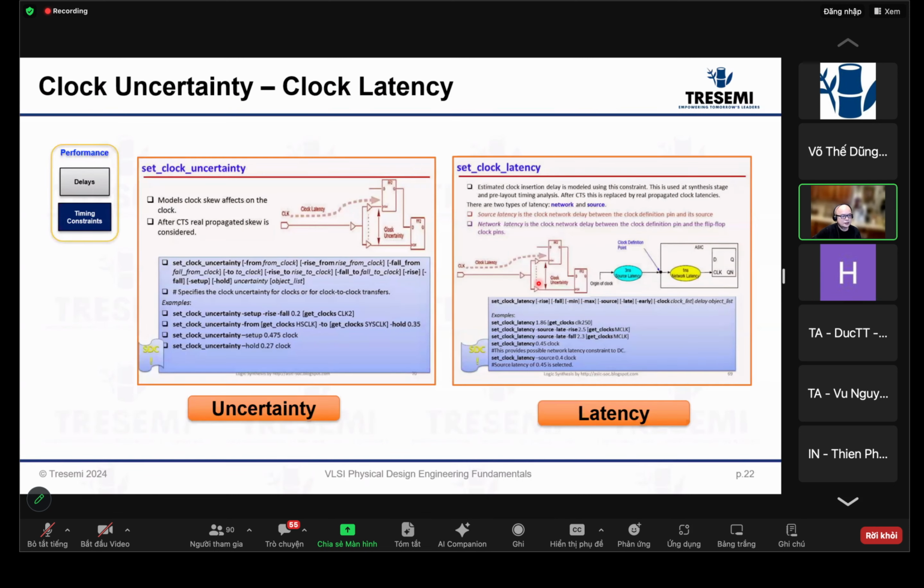So just know that. Then you will also learn the concept of clock uncertainty. Uncertainty is a way, in timing analysis, to model the differences and skew. Also, if your clock is generated by an on-chip PLL, a phase lock loop, then the actual edges of the clock, due to the operating conditions, will not be the same all the time.